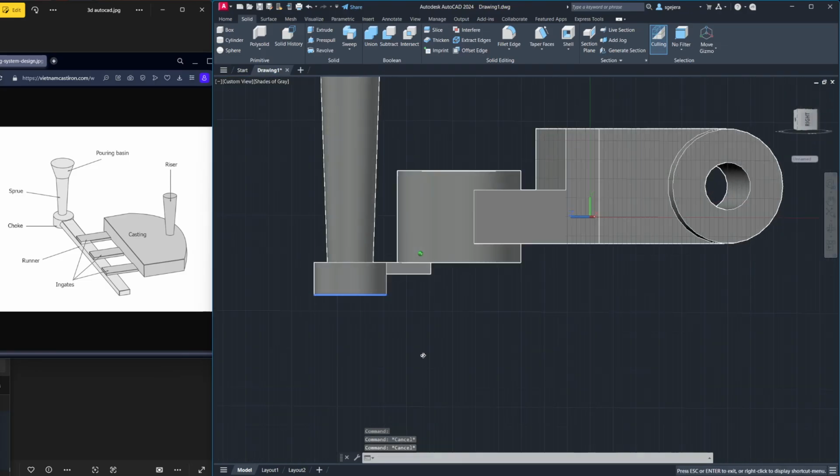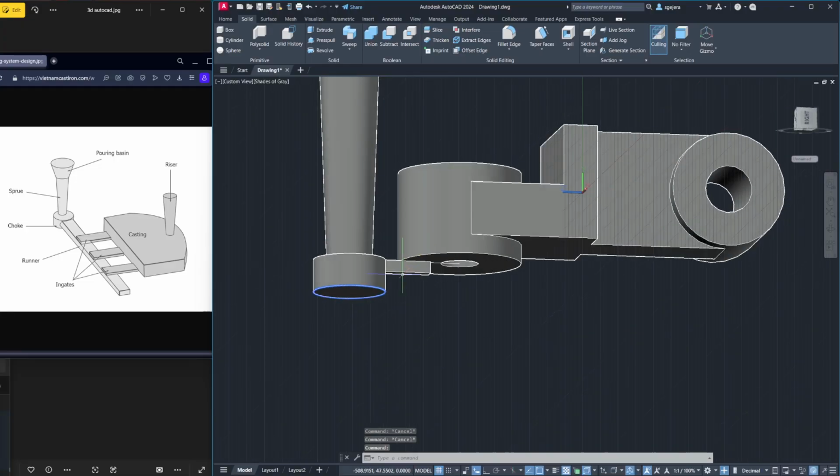This is a bottom gate ang tawag dito, no? Because it's feeding from the bottom and it moves up. Maganda dito is that it's laminar yung flow niya, no? Kasi smooth yung flow niya from down dito, pupunta siya dito, it feeds upwards papunta dito, making it a very smooth flow as opposed to a top gate wherein yung top gate naman pagka kunwari, I'll just move this upwards. Kunwari ganyan. A top gate will look something like this.